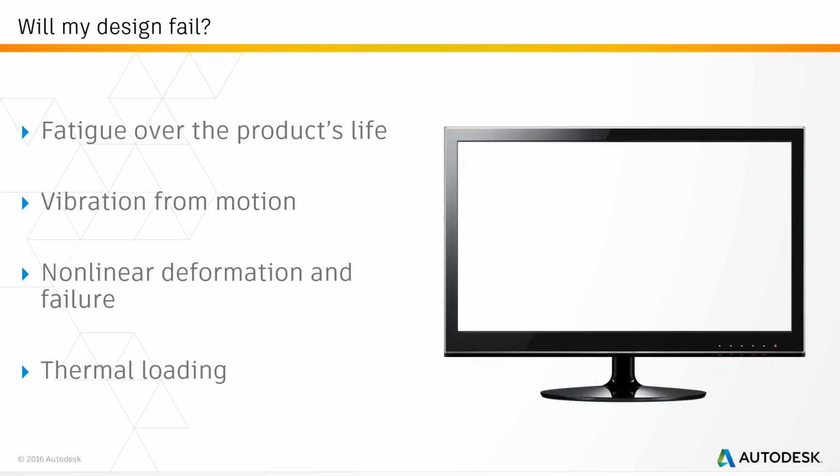Will it be subject to vibration from any motion? Can this cause failure? If it exceeds the yield strength, the loads are higher, will the deformation be excessive? Will it be recoverable? Will it be subject to temperatures during service, which can cause thermal stresses and cause it to fail?